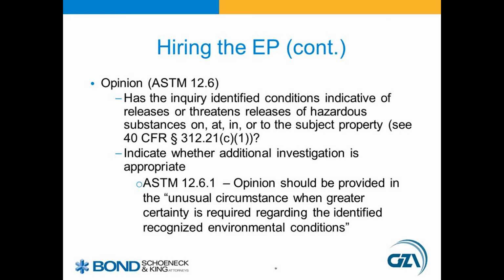An example of where an environmental professional may recommend additional investigation could be a case where the property was used as a retail gasoline station 20 years ago and has since been decommissioned. However, there are no records or documentation of tank removals, soil sampling, or regulatory oversight. This would be considered a data gap and could be filled by a subsurface Phase 2 investigation.